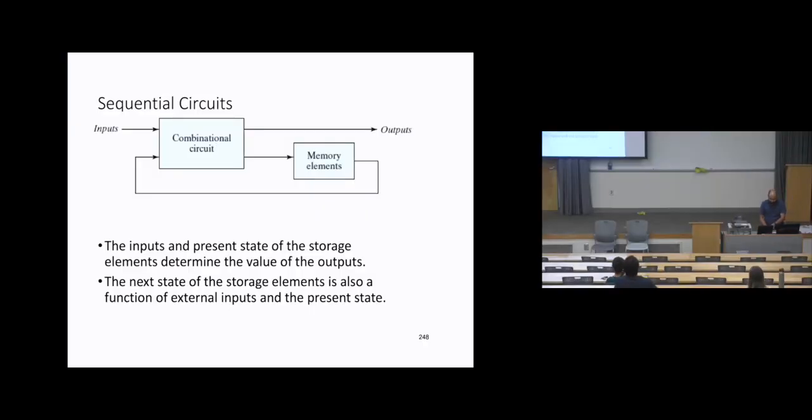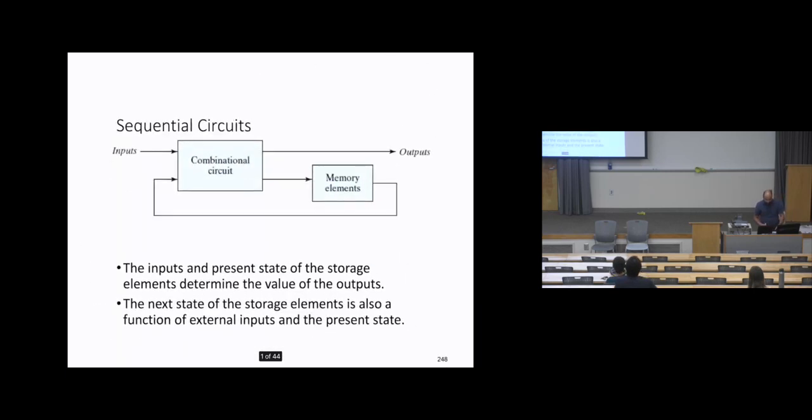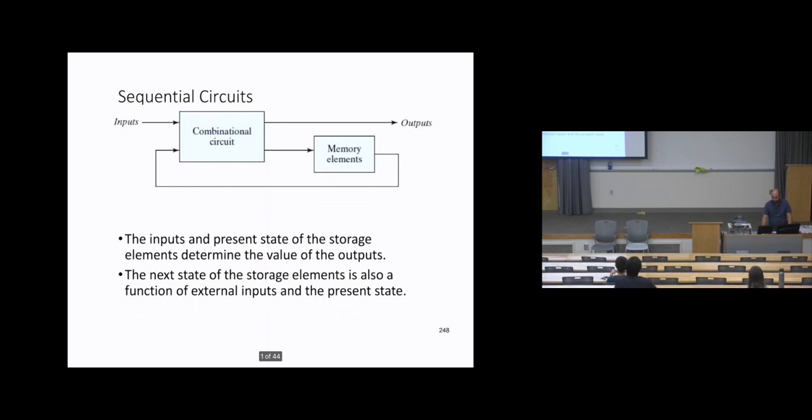So today's lecture, we will start a new chapter, which is chapter 4, Sequential Circuits. The previous lectures, the first half of the course, were about combinational logic circuits, where there is no time dependence, no feedback, no memory, no storage elements. But in sequential circuits, there is a memory element, or something related to time, or there is a feedback.